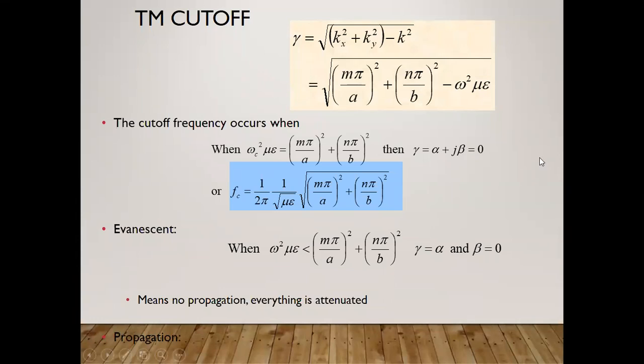How we can write the expression in the form of the propagation constant, alpha and beta. We can find the angular velocity, we can find the cutoff frequency by 1 by 2 pi root of LC, that is nothing but the resonant frequency f0 is equal to so and so. Similarly, we can write the expression not only for the propagation constant but also for the cutoff frequency.